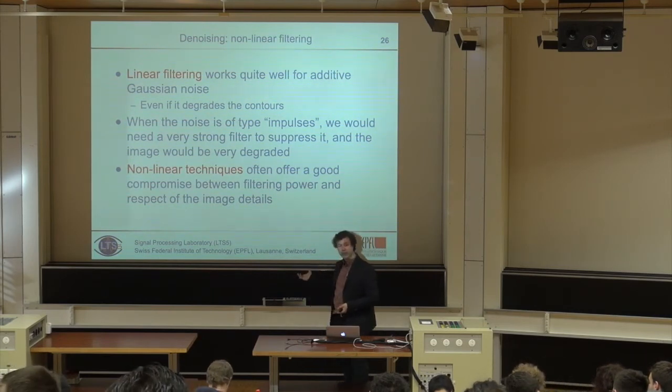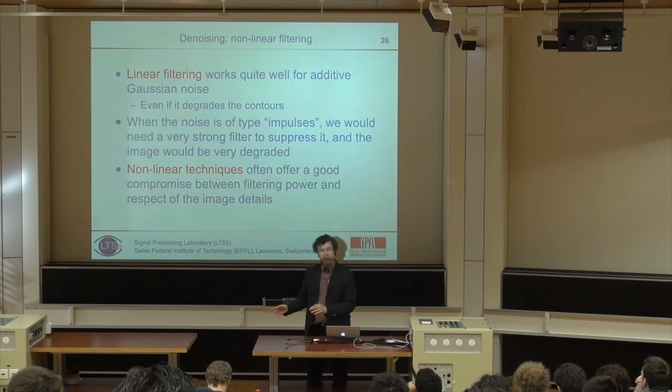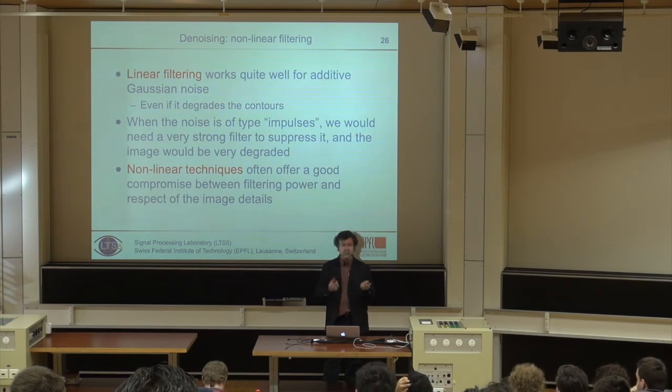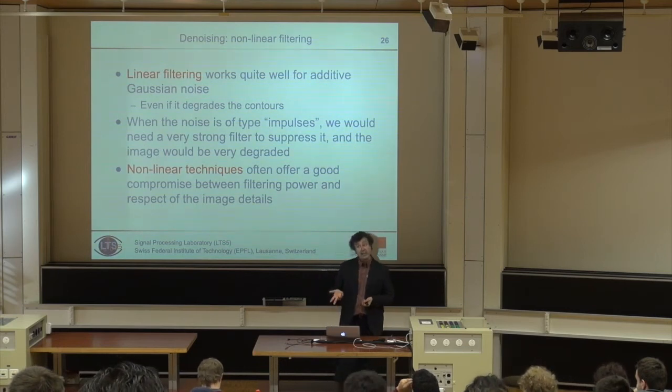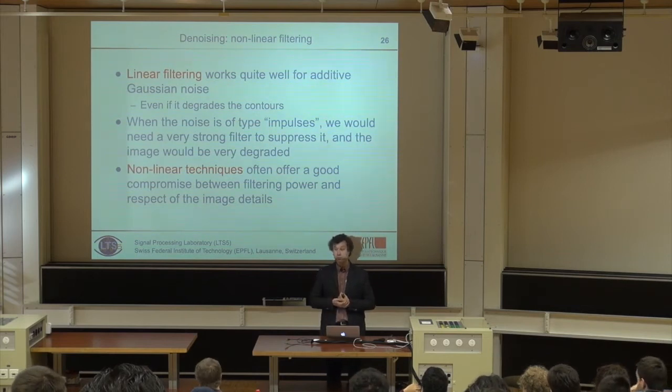Some of them I will let you read in the slides. One of them I will focus on. So, linear: you take a filter, you convolve your image with that filter, you get a result. Drawback of that, you cannot really select whether you degrade the image or the noise. You do what you can. Advantage of that, what is the advantage of doing a linear filtering, a convolution? What could be an advantage of filtering an image with a linear operator? How do you do a very fast convolution?